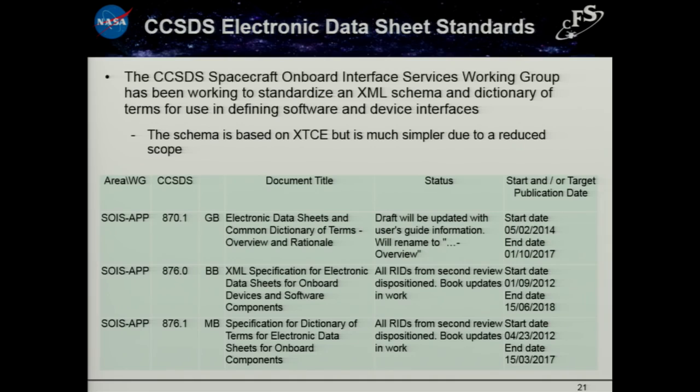Or 1553 subaddress has a real meaning in that protocol. So those are defined in the dictionary of terms. So you can use them in your data sheet. Say this device talks on 1553, uses subaddress 25 and sends this many words, and here are the formats of those.